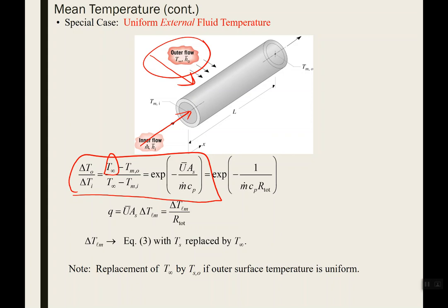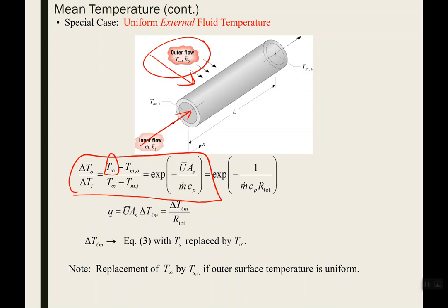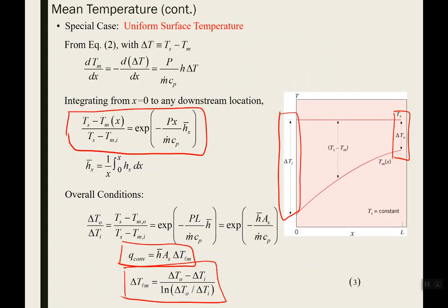So to find the H's, you would use convection correlations. Those would be a function of Reynolds number and Prandtl number. The H's themselves, you wouldn't need to solve for the outlet temperature first. You could just calculate the H's. You might have to take a guess value at temperatures to evaluate thermal properties.